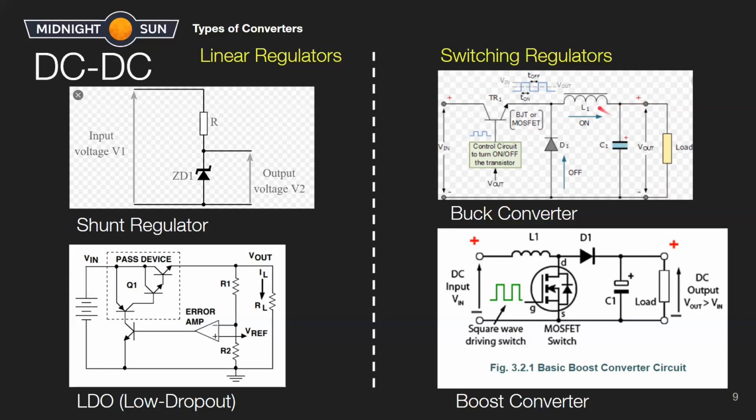And so while we're pulsing this, we're getting an RMS value that's basically at a lower reference. And so we are bucking the voltage on the load. So yeah, that's how it works mainly. And you'll see that again, we'll be seeing a kind of triangular ripple on the output of this load after filtering it with capacitors and such.